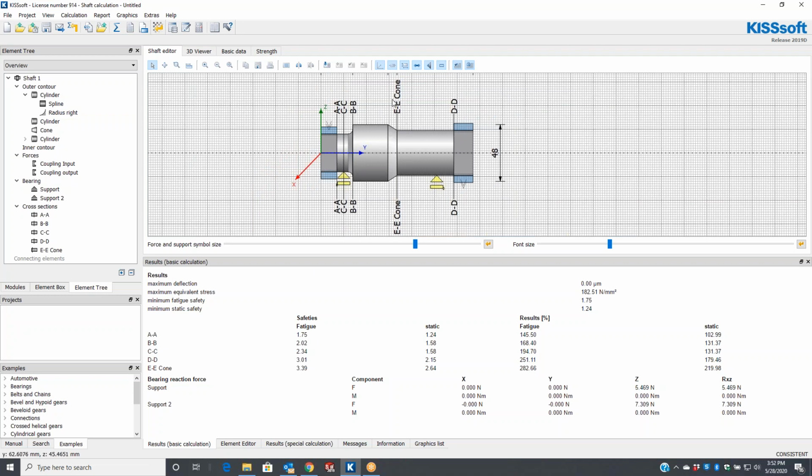So that's how you would set a free cross section and how you define your own notch factors. Pretty easy to do. Play with it. See if it affects your FE calculations. Something on a simple shaft like this, that FE calculation takes maybe a minute, if that. But good luck with that, and hopefully you're staying safe during the COVID.